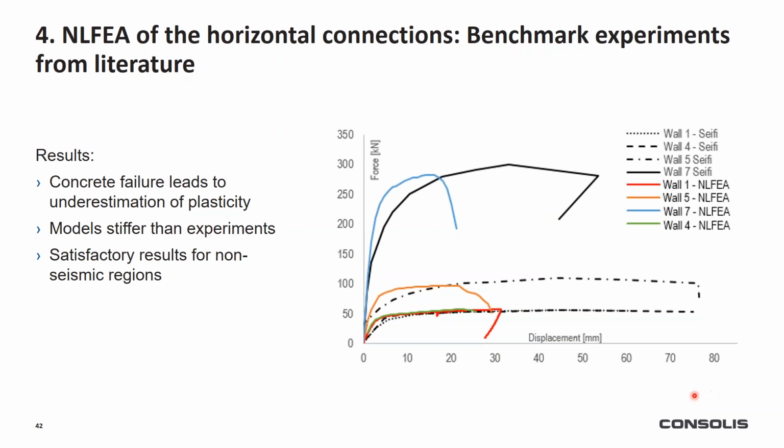And here are the results. Initially, there was a quite good match between the model results and the experimental results provided by the authors, but at higher axial loads, when we had the failure governed by concrete crushing, the model started to behave in a stiffer manner, and I was unable to fully capture the plastic behavior.